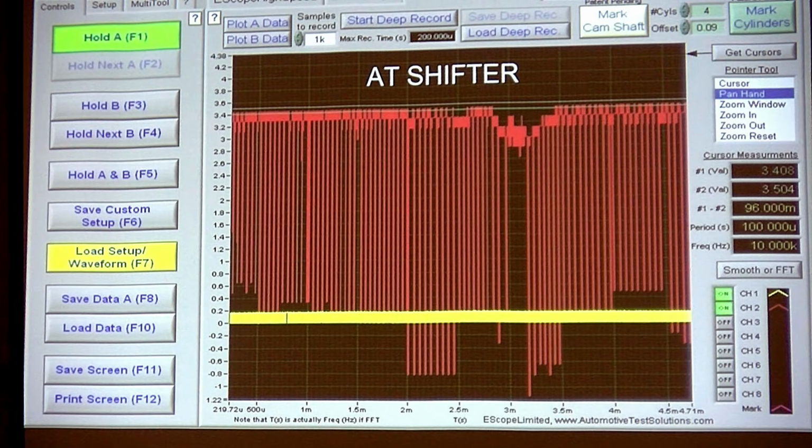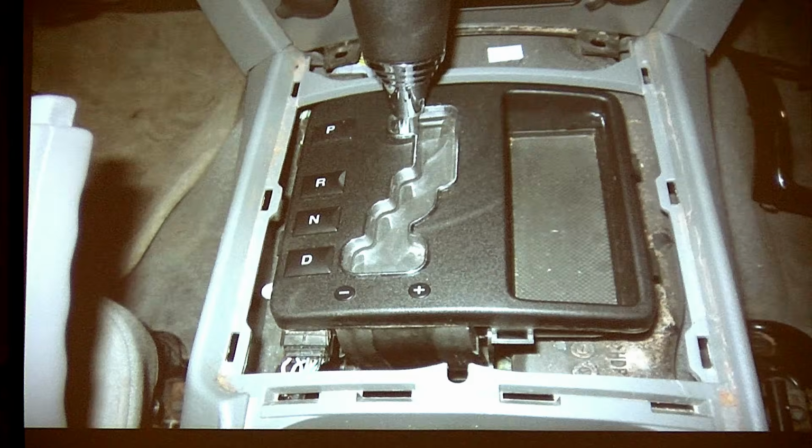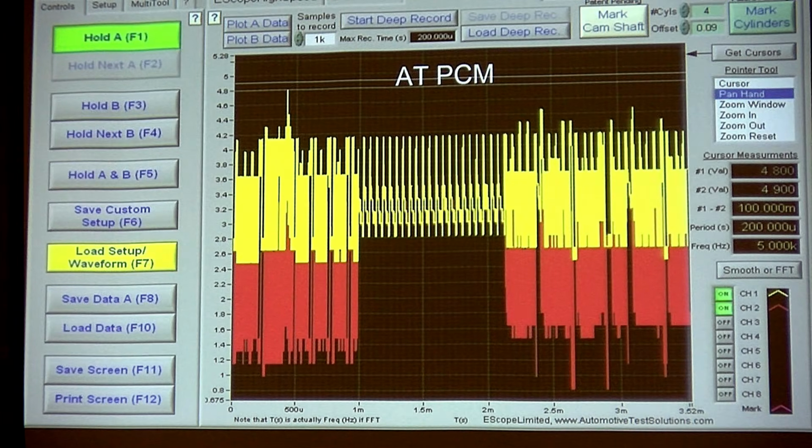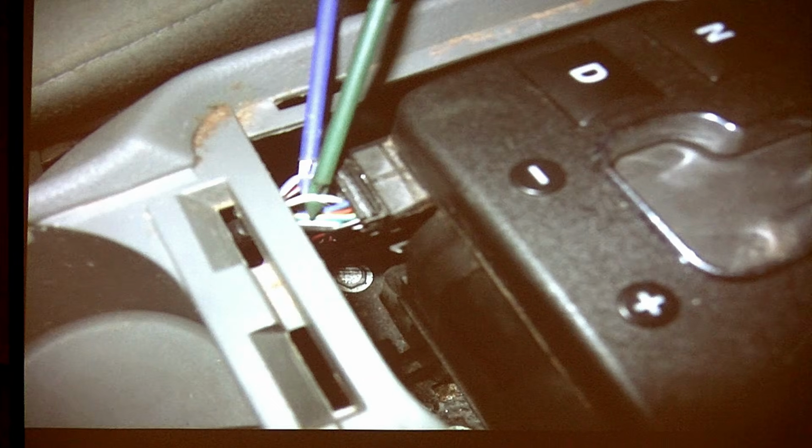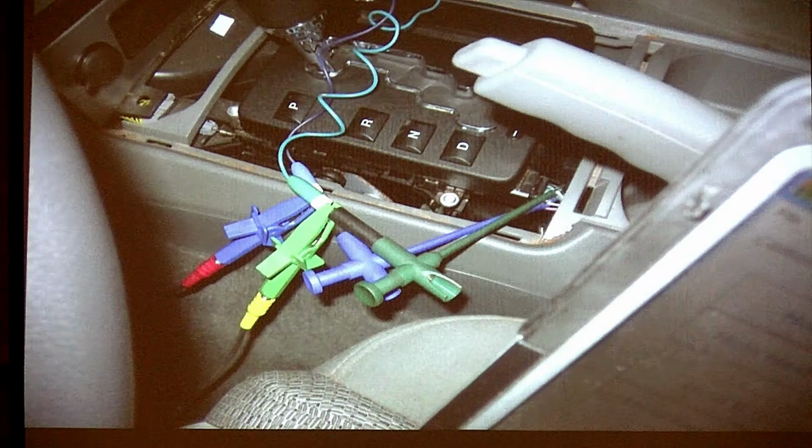Those wires are not good. One of them is broken and one of them is made, and now it rings. Notice that this waveform that you see right up here, do you see that that's what's riding over here? It's the same signal, but you only have one wire that's doing it. The other wire is open. So now, I've got this figured out.